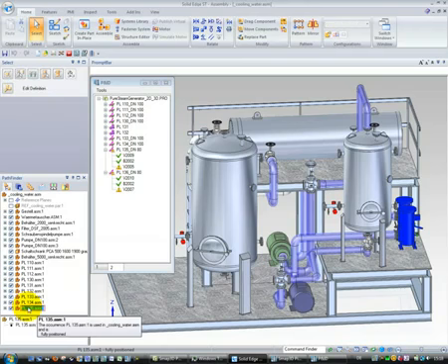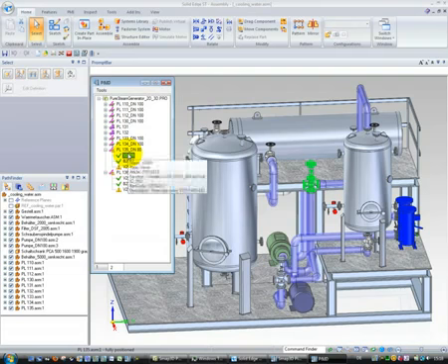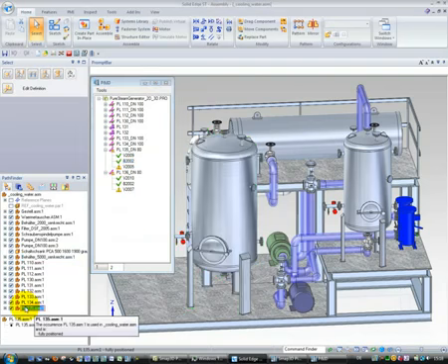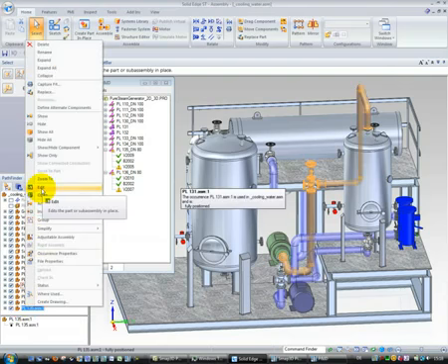In this subassembly we are now able to create the pipeline path. And from the Pmid mask we can see that we have to create a pipeline path from this valve, the 3D assembly valve, to this vessel. So from the Pmid I get delivered from where to where I have to draw my pipeline path. And with this information I go into my subassembly with the edit mode.